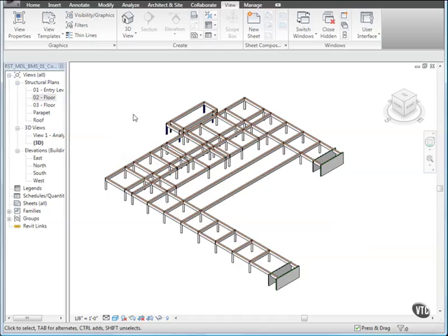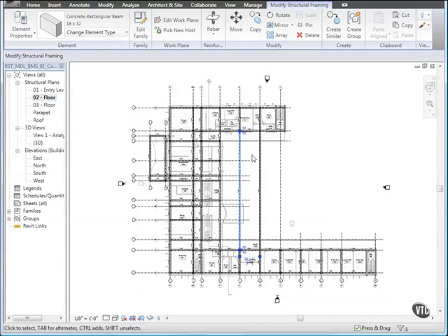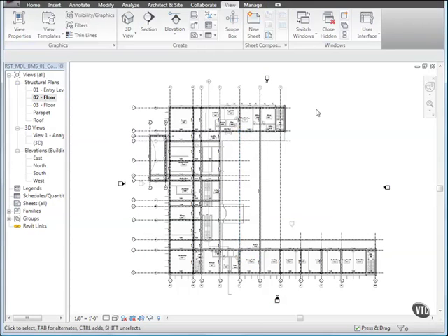and let's delete the beams outside the drawing floor extents. Go back to the Structural Plan View 02 Floor and select the beam placed on grid line 4 as shown. Then, on the Modify panel, click Delete. Using the same method, delete the beam on grid line 5.